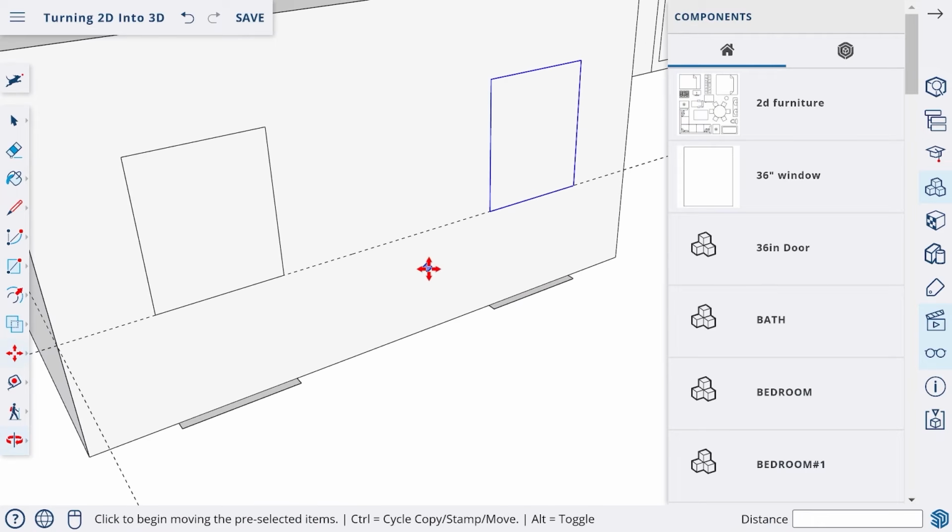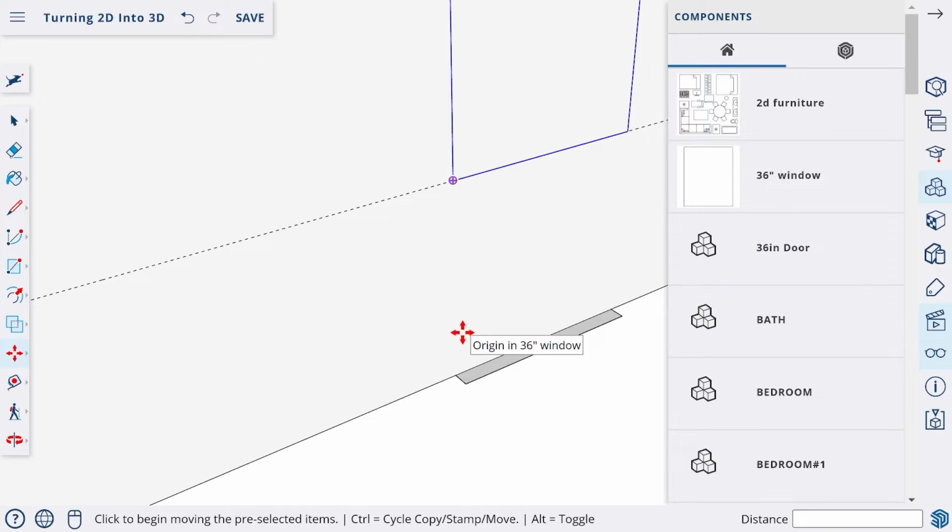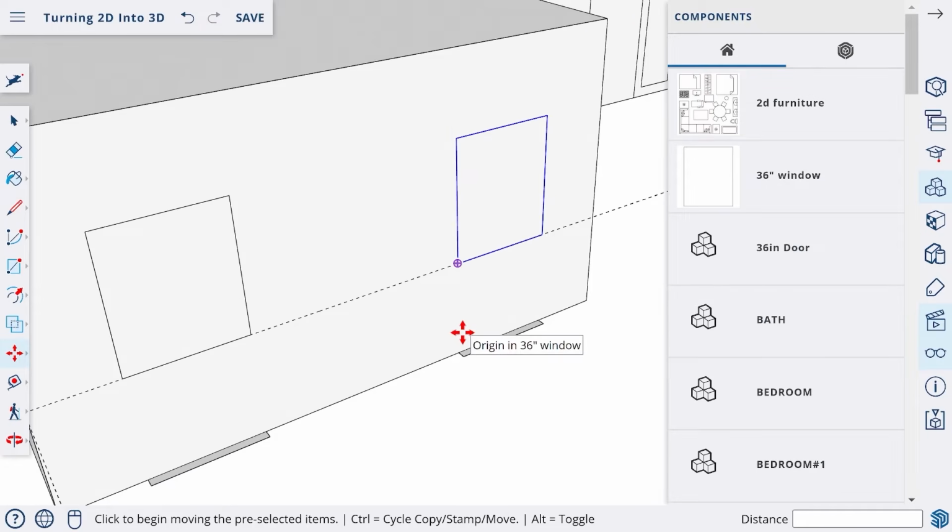So a lot of times the camera position will dictate how SketchUp wants to snap and interact with some of your other objects. Again, the tip here is to be patient. Moving around and navigating the model, placing those guides, dropping the component in, it takes time. But practice and working with precision will really help. The better you get at zooming in close and moving out a little bit will make it much easier to work and navigate within SketchUp.